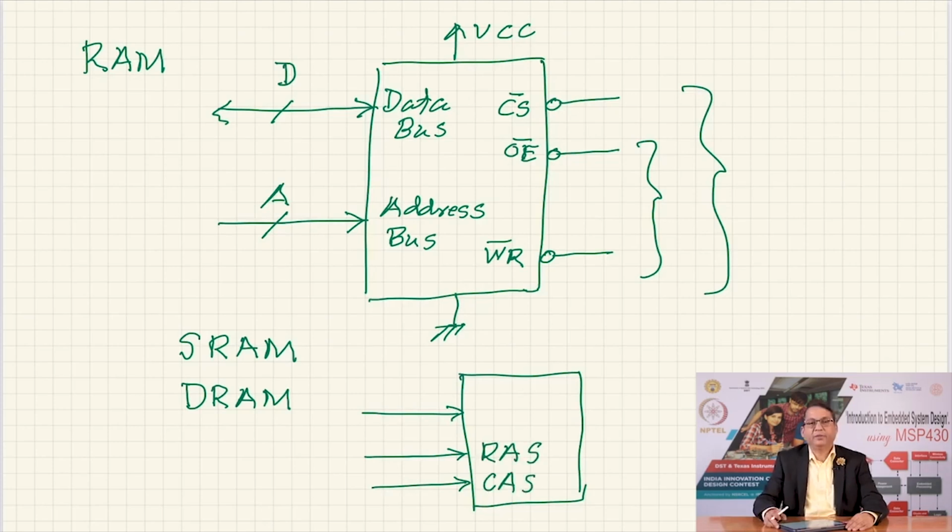So it's like the memory is arranged in the form of an array, and first you supply the row address, then you supply the column address using the same address lines, and so the number of address bits required to access this memory is reduced. You also need to frequently refresh the contents, otherwise it would lose the contents and therefore be useless as a RAM. And so using it is slightly more complex, but because it is more efficient, it's more dense. Modern applications often use DRAM chips. If the requirement is small, then you might go with the SRAM.